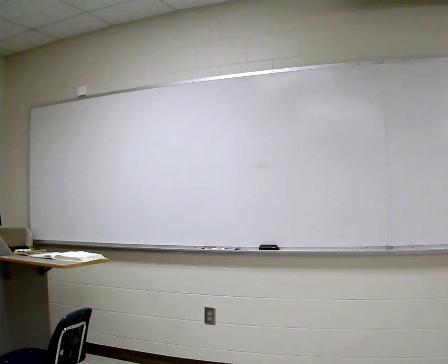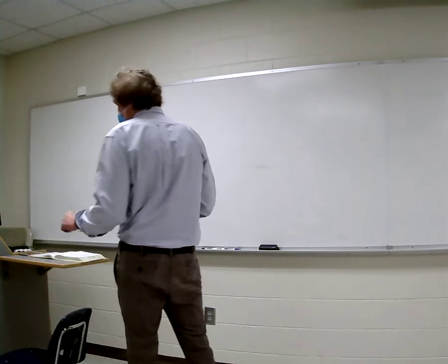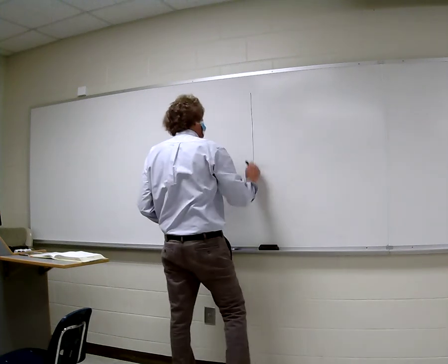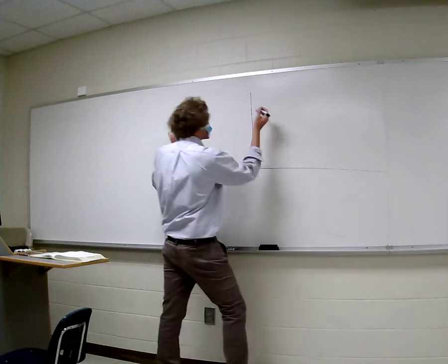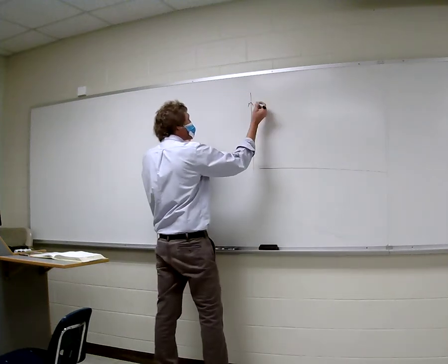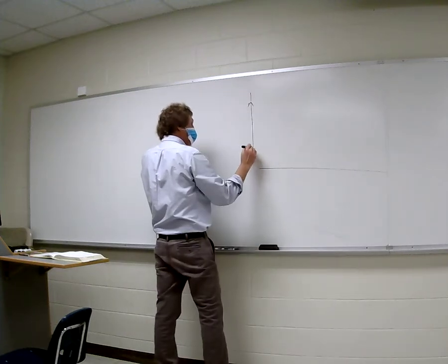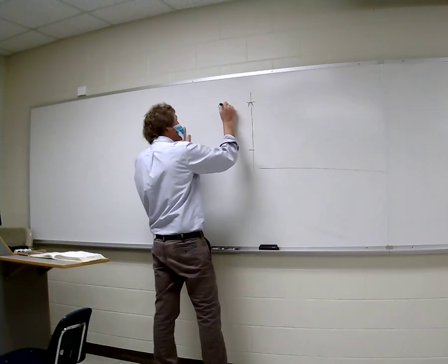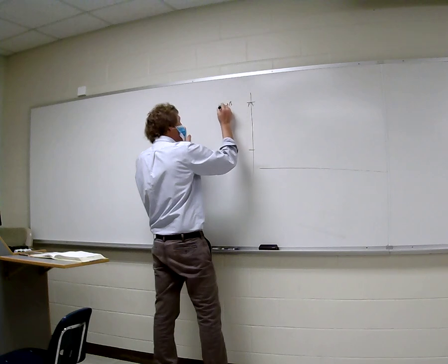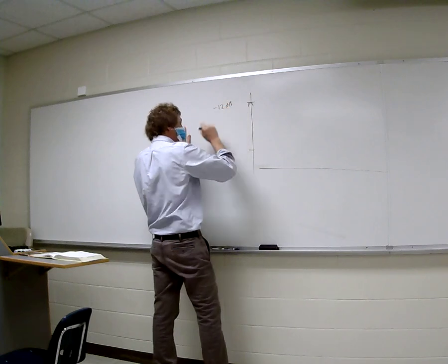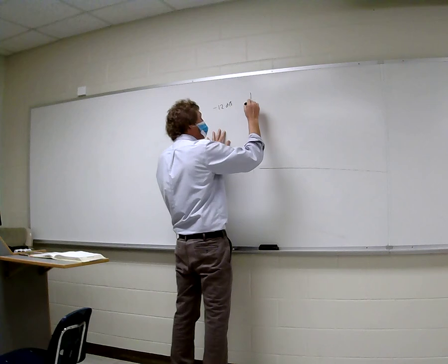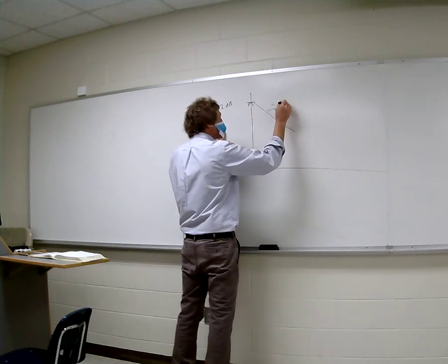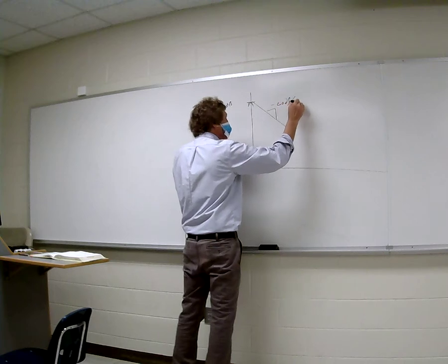Is this asking for a function that can do it? Yeah, so it starts on the y-axis at negative 12 dB, and then it goes down at negative 20 dB per decade to 3 on the frequency axis.